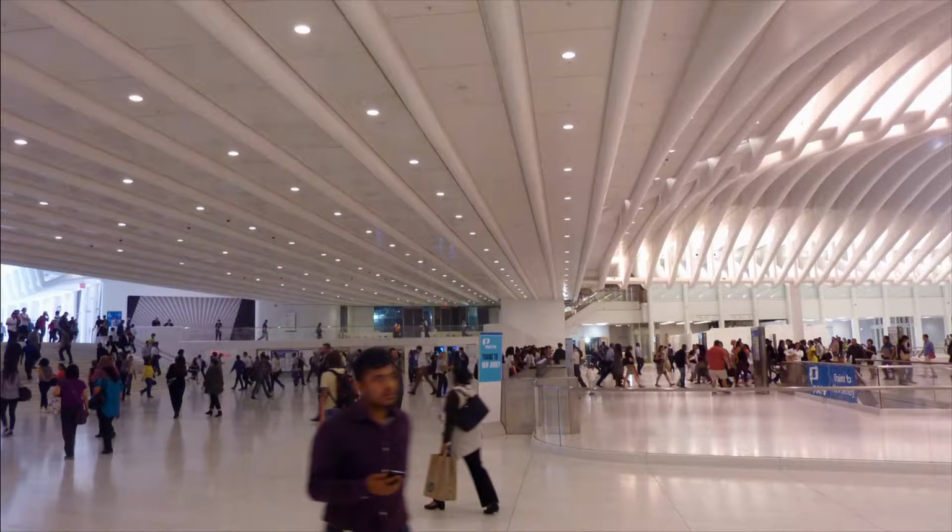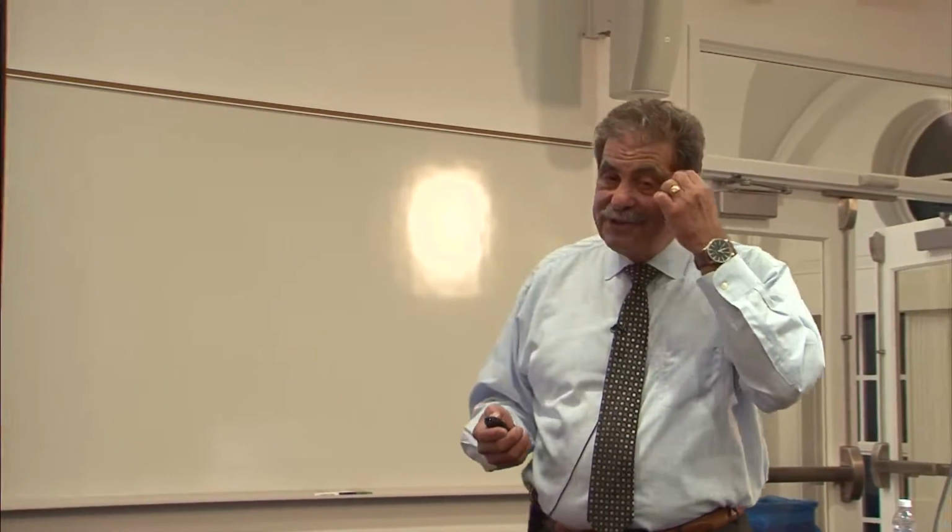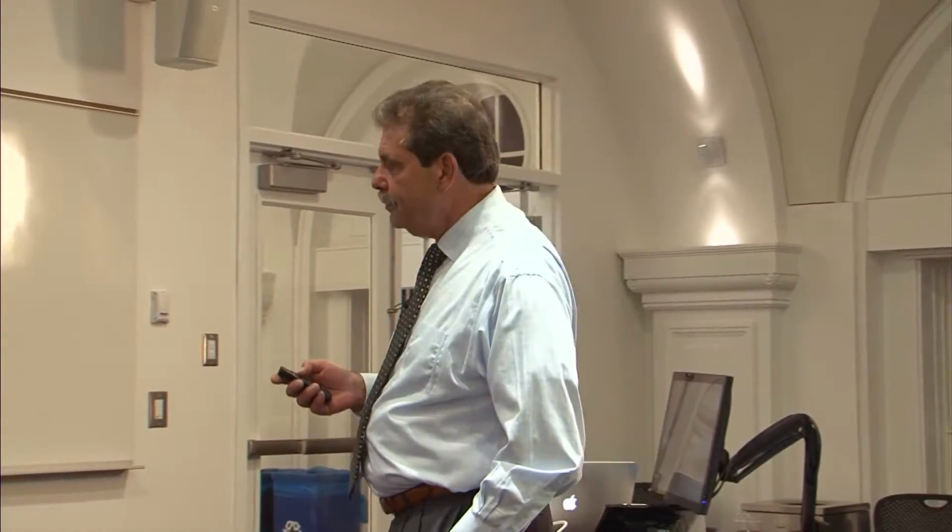Talk about complications. 2 codes. Everything beyond that glass wall, that glass rail line right there, is NFPA 130, 1 code. Everything outside of that is New York City building code. All right? It is a virtual separation. I actually got to use that word in practice. We have smoke control, water fire protection systems and the like, alarm systems. Everything is designed so that once you step through that barrier, you're in a totally different environment. It's controlled totally differently from the environment you just came from. But that one line's going overhead and there are 2 levels below you.